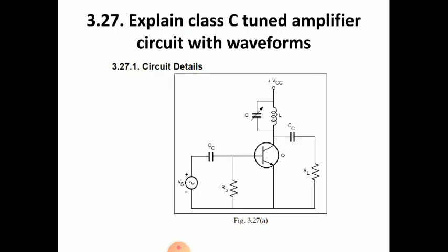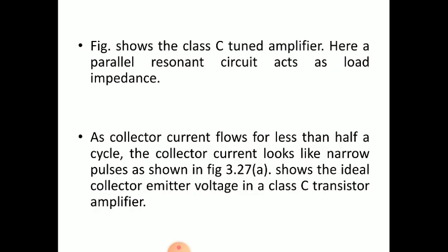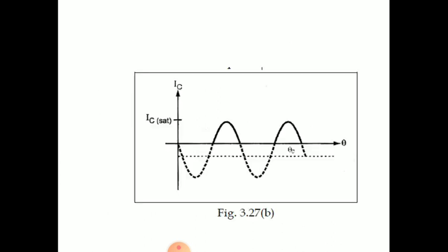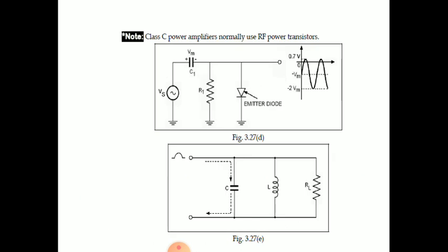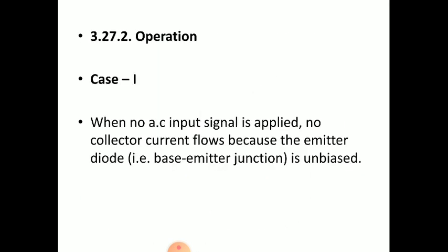If these pulses are applied to the capacitor and the base emitter junction, which acts as a diode, the circuit functions as a clamping circuit. These pulses are shifted to a particular voltage level, that is 0.7 V in the case of silicon, and are applied to the tuner circuit.